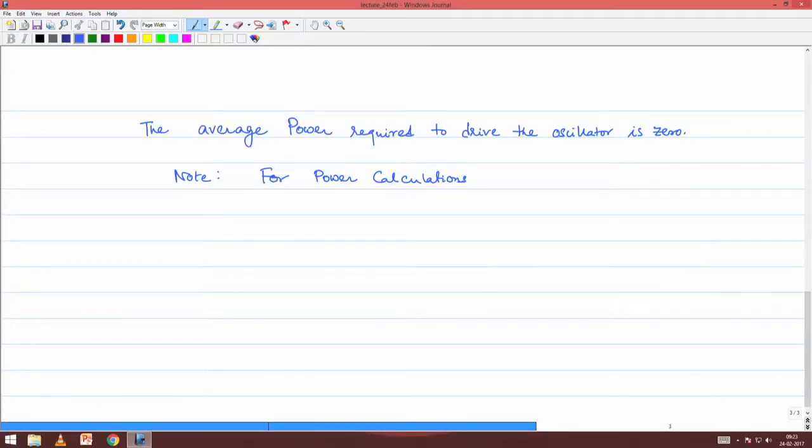Power is a quadratic term, it is a product of force and velocities. Not just the magnitude of force and not just the magnitude of velocity, what is extremely important is the phase difference between the force and velocity which rules the power calculation. So, this will also happen in the acoustic case. That is why I took a few steps backward to illustrate this for you.